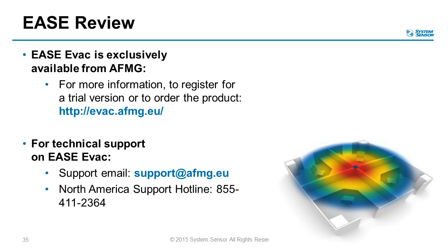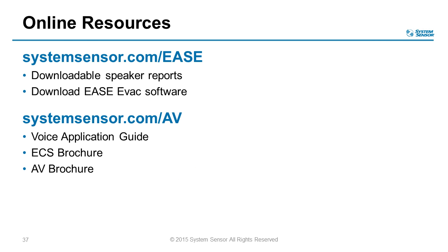In fact, what you would want to do then is for a masking system, you have a design criteria that says what that level is going to be for the masking system. You would then be able to import that as a noise level, whether you measured it or you knew what the actual values were, and then the software would tell you what the result would be with regard to intelligibility.